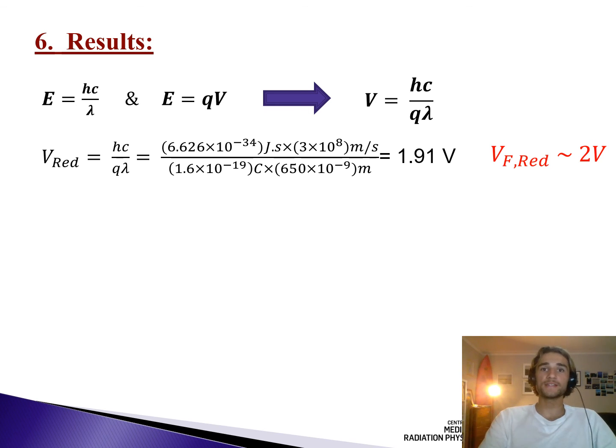One way to improve this experiment is to use a more advanced oscilloscope with smaller time steps to gather more data points. This means that the average currents used for each voltage are improved since the weight of any outliers are reduced. Another improvement would be to minimize fluctuations in temperature, since Shockley's equation states that the current intensity is dependent on temperature. Diodes are significant because they're used to control and regulate all electrical devices we use today.